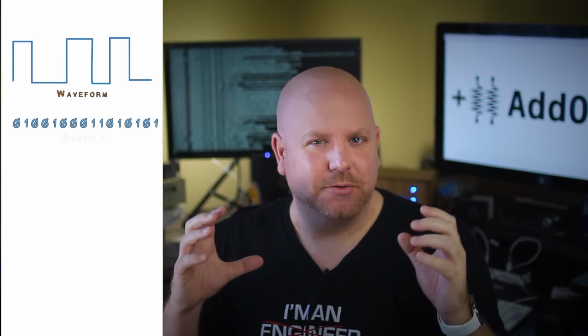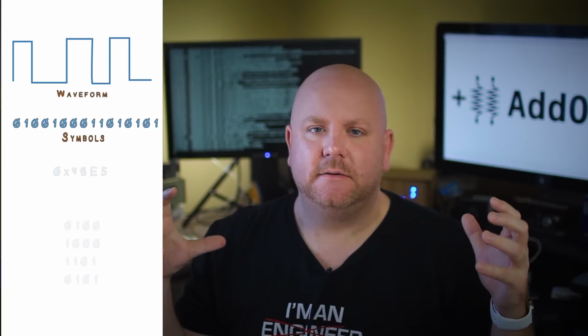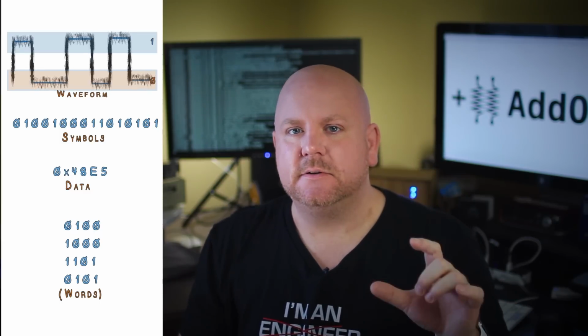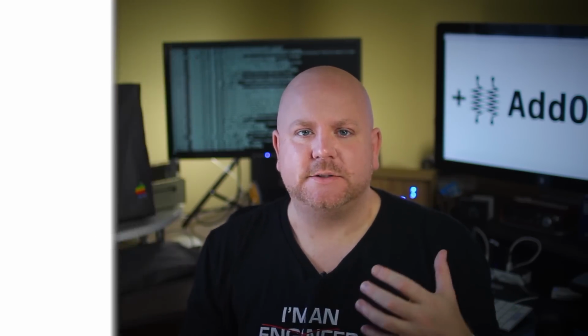So while in theory a pure analog waveform is a fantastic way to transmit information, it's really not possible. So when we look at digital, it is just defining some voltage levels that create ones and zeros. And so sometimes we'll call those symbols. And then you put a whole bunch of symbols together and you get data or words. And so what that allows for is we can put a lot of noise on the signal and we can still recover the original data. And so digital is really an analog waveform, like I said in the video. It's just that it's been encoded with some information.